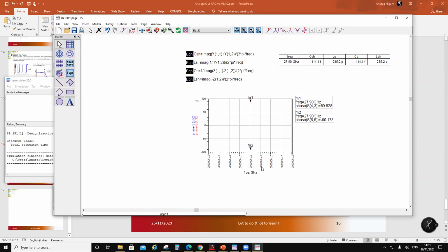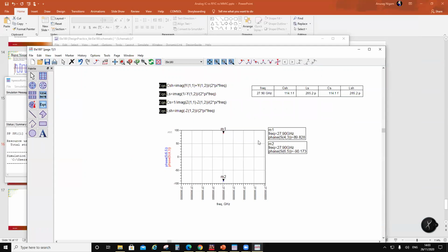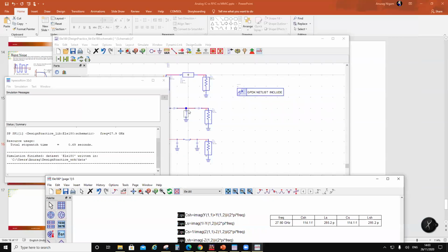Design is very simple, unless you think the scientist way of doing things, and you go and read thousands of papers and try to find formulae for high pass element design and low pass element design. Why? You are an engineer, right? An engineer knows how to get the job done. I got my job done by just putting an ideal line and using the T pi equivalent, and I have my design elements. Why do I need to write an elaborate formula for computing C and L? That's the difference between a scientist and an engineer.